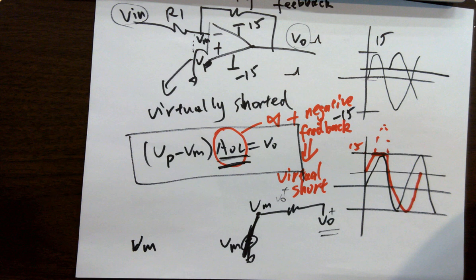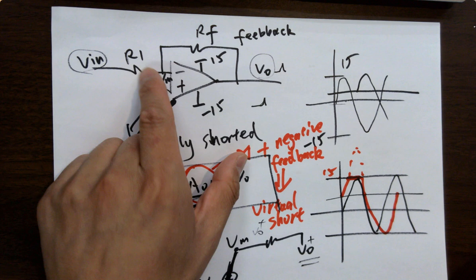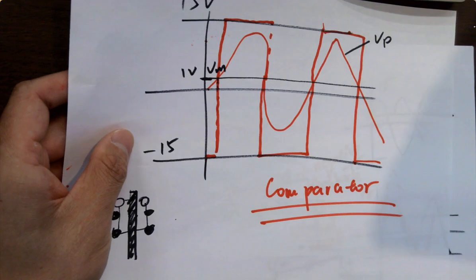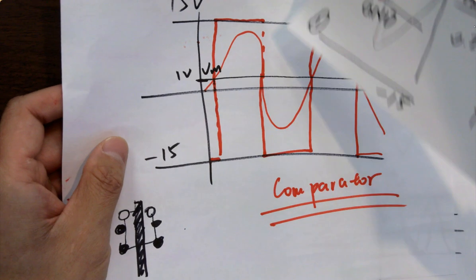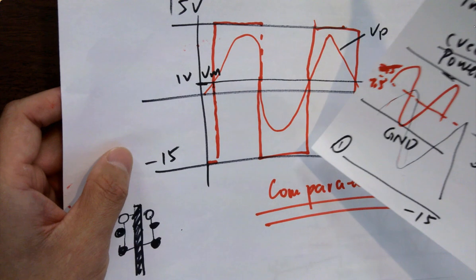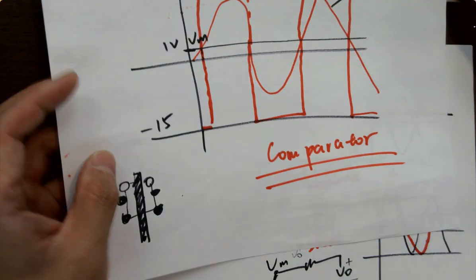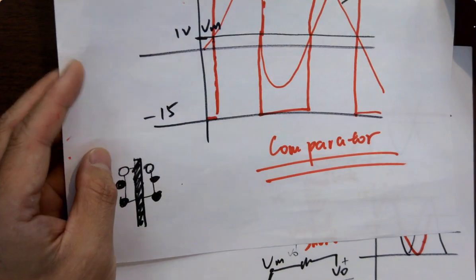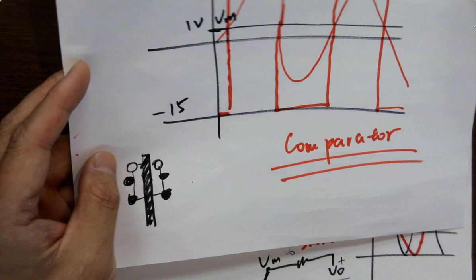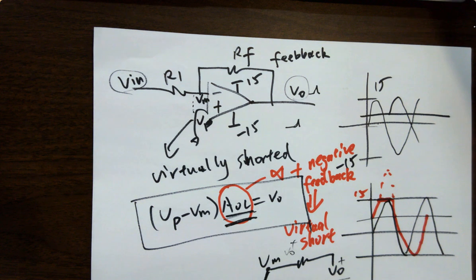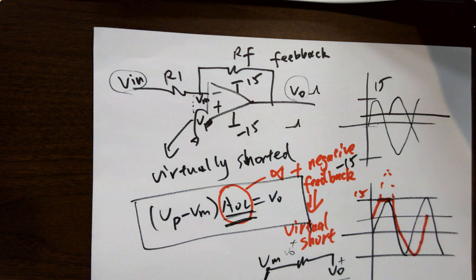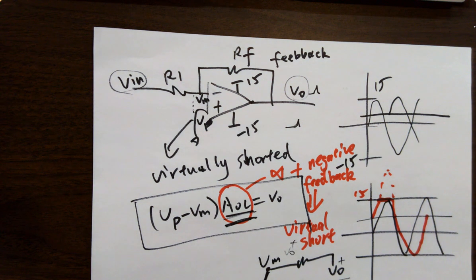What would be a use for something like this? Sometimes you would want to amplify the signal, unlike a comparator. You want to amplify by 3 times, 2 times, 4 times, instead of a digital signal. You don't always want a digital signal, do you? If you are amplifying an audio signal like a song, you want to hear a song, right? You don't want to hear a boom boom. So it should be a song, a time varying signal.